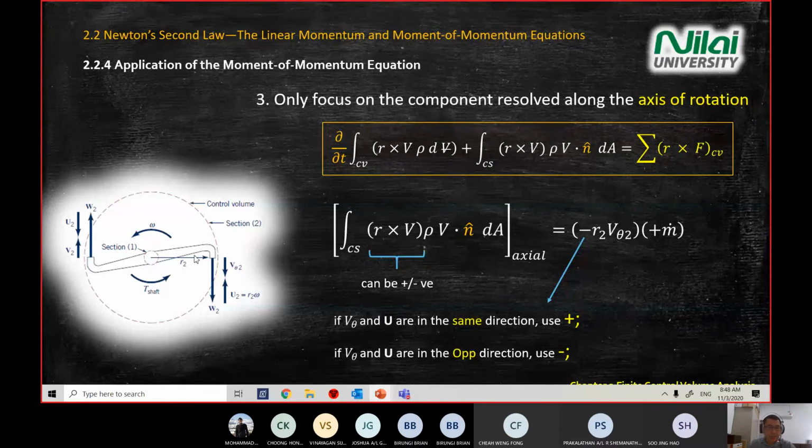Now in this case, we have a negative scenario. On this sprinkler, the flow will come out from this end of section 2. The water will spray out in this direction, so our absolute velocity will be coming this direction. However, if you sit at our U2, at this location, and you look at this nozzle, it will move anti-clockwise.